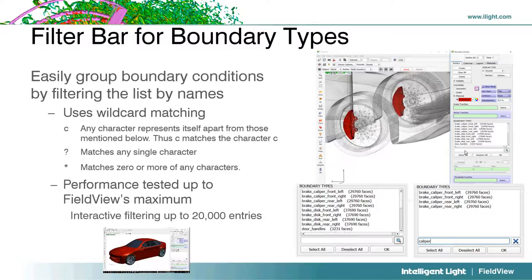If it's too late and you didn't have the chance to do that, another trick that I've been using has been to append to your session the geometry in a different form. You may know that FieldView has an STL reader. STL is a common format used by CAD tools.